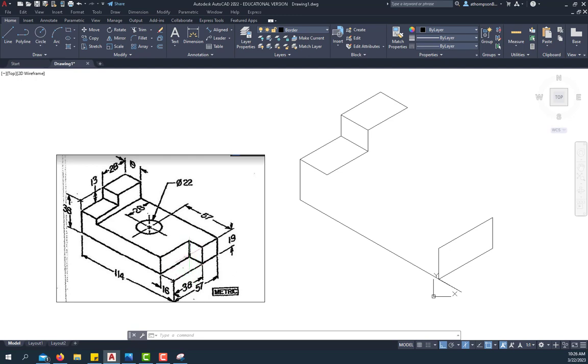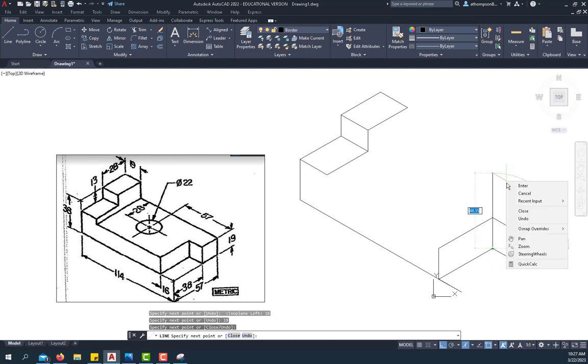And then I know from those points I can come back out the 16 and finish up this little surface here. So I'm going to click on line again from this corner. I have to hit F5 because it's not letting me make that width dimension. That's 16. Enter. I'm going to go down 19 with a vertical line, and then that should come back to connect.